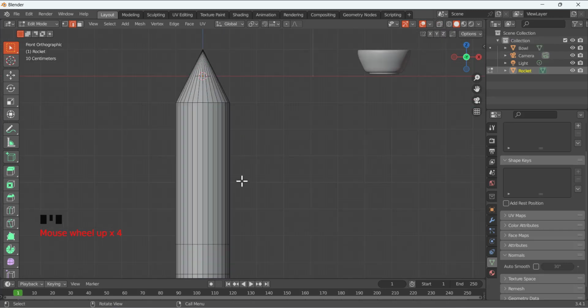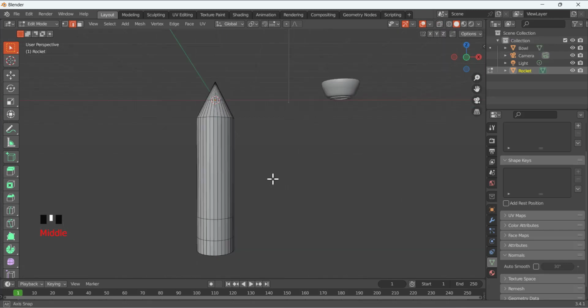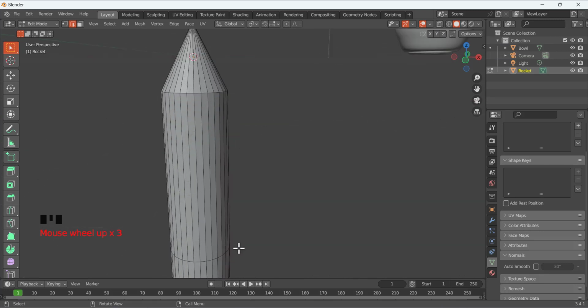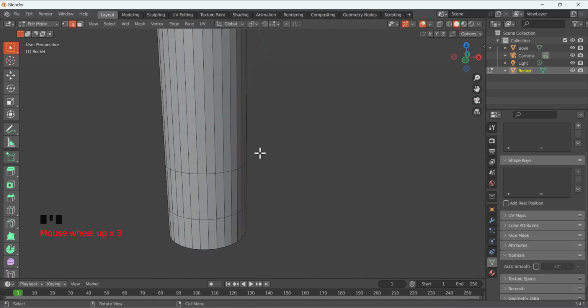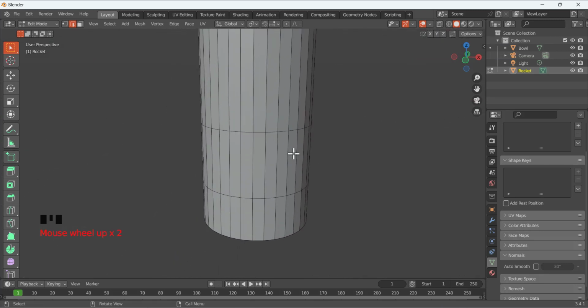Now deselect the X-ray view and then rotate this model, then zoom, then pan, to see these faces. Now I want to select this whole ring of faces. I press the Alt and this. Sorry, we need to go to the face mode. So select this face mode, either by pressing the 3 or going here. Two ways.